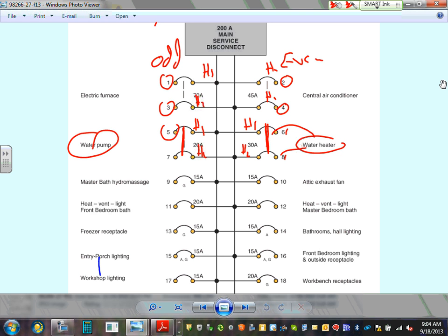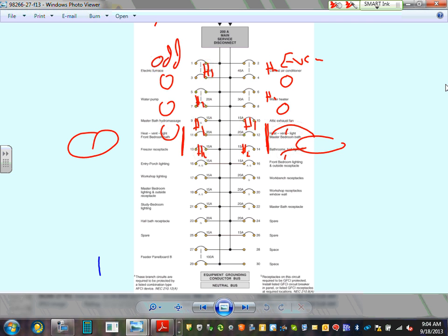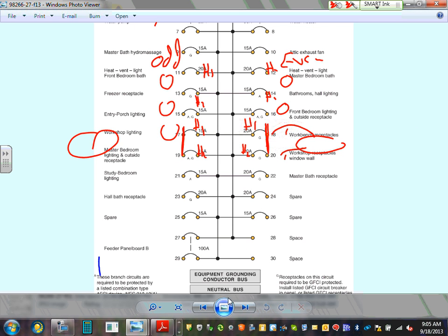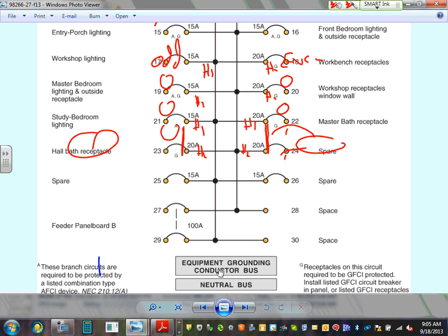The odds and the evens. That's how they make it. So then you can take 1 circuit breaker with the neutral, get you 120. 2 circuit breakers with or without the neutral can get you the 240. Okay, here's your equipment. And then at the end, they have 2 bars here. 1 for the equipment, 1 for the ground. And if it's a service, they bond them together.